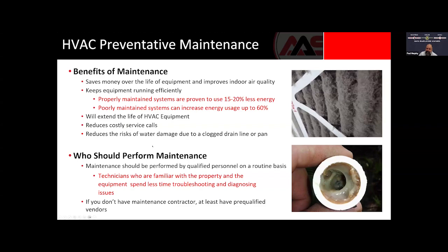Preventative maintenance. We want to talk about preventative maintenance because that's some of the common issues that we run into with units, which is just clogged drain lines and clogged filters causing fan motors to die. So make sure that you're doing your maintenance, changing those filters at the recommended frequency. Now, everybody's frequency for changing filters could be different depending on what kind of pollutants you have indoors and how many people are moving in and out of the building.